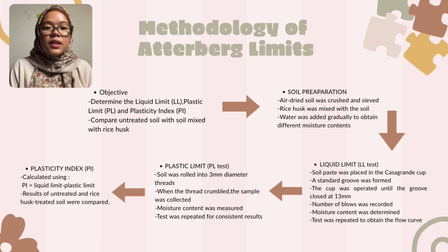Finally, the plasticity index was calculated using the formula plasticity index equals liquid limit minus plastic limit, and the results of both soil samples were compared.